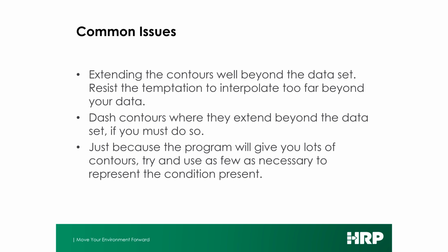If you have to go outside your comfort zone of the data set, dash them. Particularly if you go beyond your data set in the down gradient or up gradient direction where you really have no data. Extending them laterally a little bit is a little more justified, because you do have a line trend there. Oh, here's another one.